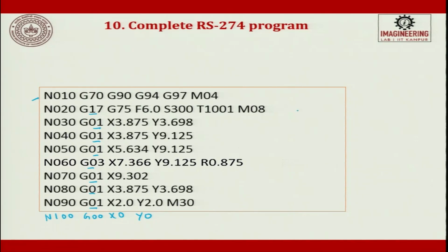So, it takes us completely outside the component. Here you can write it in R plane, R radius, or you can write it as I and J options. Please keep that in mind, and just for simplicity you can start using R rather than I and J. In the examination, if a program is asked, it is better you use R instead of I and J.